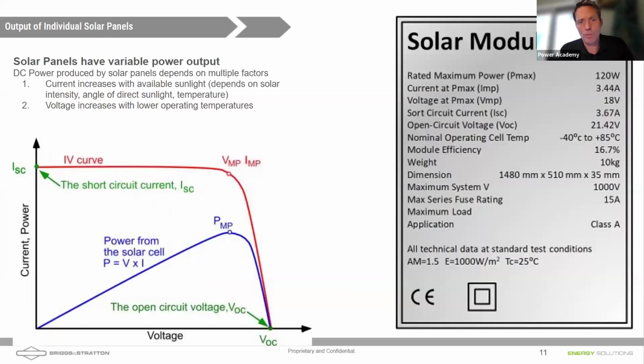What happens in a solar panel, though, is the production of electricity, and like I said, you can think of it almost as a little electron pump. If we pull all of the current off of that panel, we are essentially short-circuiting the panel, and that is the maximum amount of current you could get out of the panel, but your voltage is down. Daniel, what's power? We're a DC system. How do we compute power?